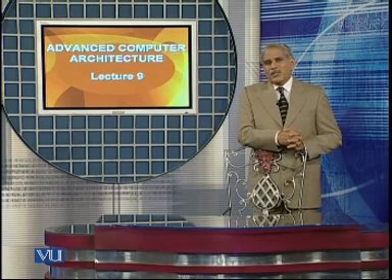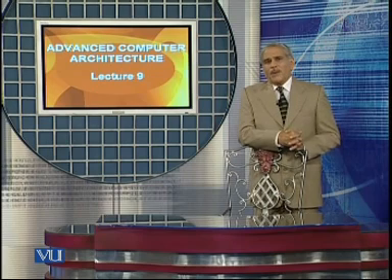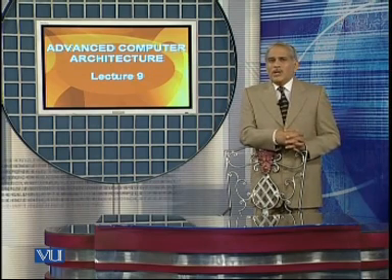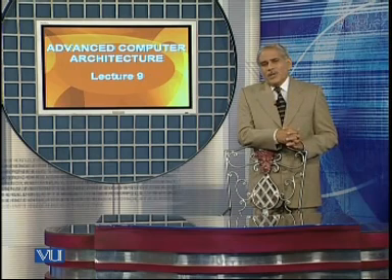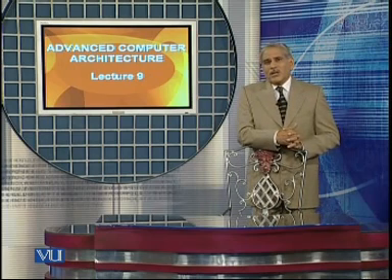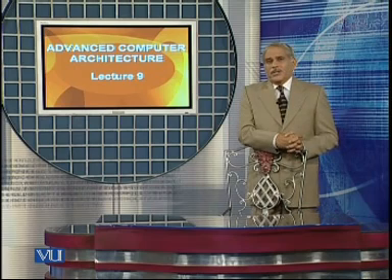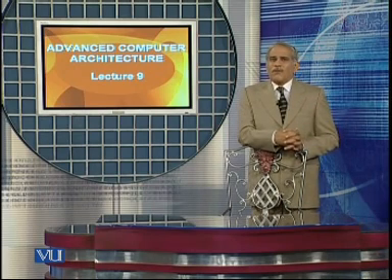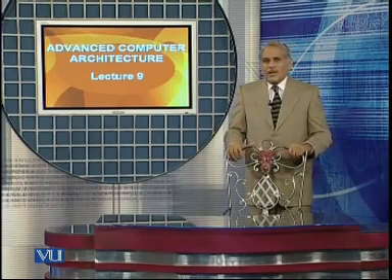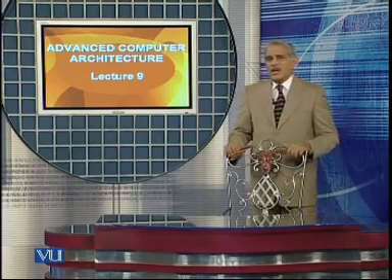So in this whole process, we can see that the load instruction is the one which takes all the 5 steps. So it takes the longest time to execute. And this is the instruction which actually determines the size of the clock in case of single cycle data path design, which we said in the beginning to be equal to 5 microseconds.